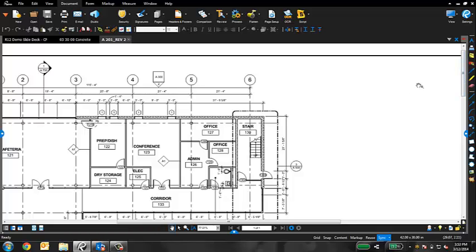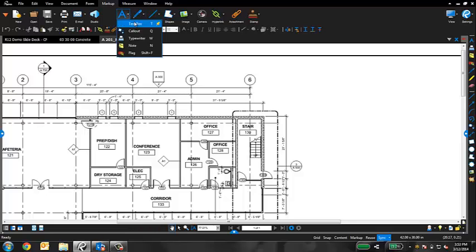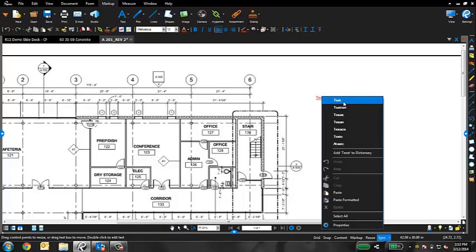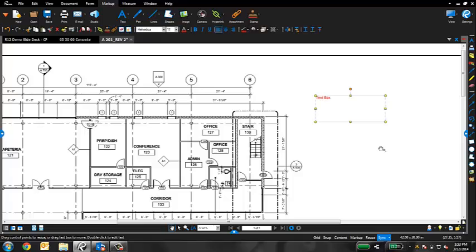There are actually three. Users can go ahead and click Markup and then say Text Box. Add a text box right here. All right, text box. And as you can see, I spelled text wrong. But luckily, Revu has a built-in spell check, so I can go ahead and right-click that, change it right to text right there. We can also use the icons along the side of the profile here to use markups.